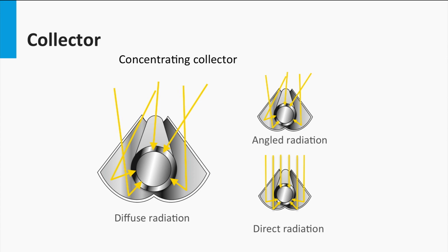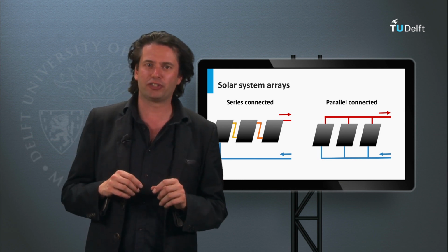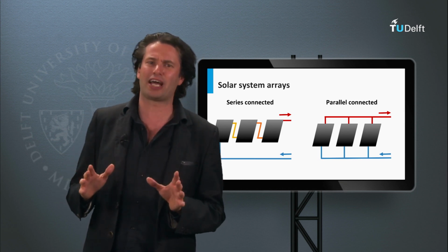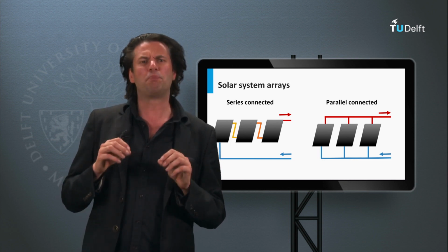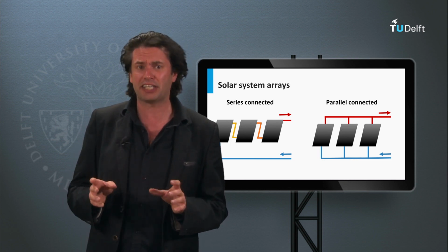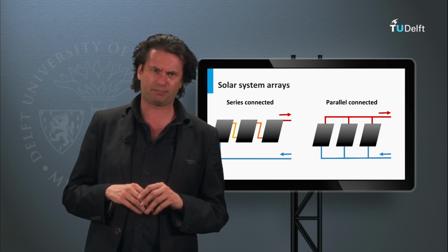Even though these configurations reduce the losses, they have extra costs and problems due to the tracking systems, both during the design and the maintenance processes. Most commercial and industrial systems require a large number of collectors to satisfy the heating demand. Therefore, a combination of collectors in series and in parallel should be created.